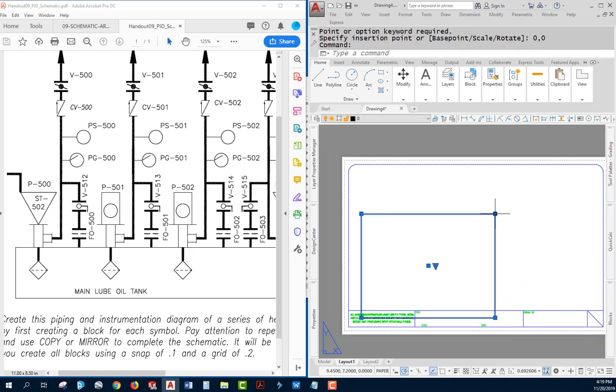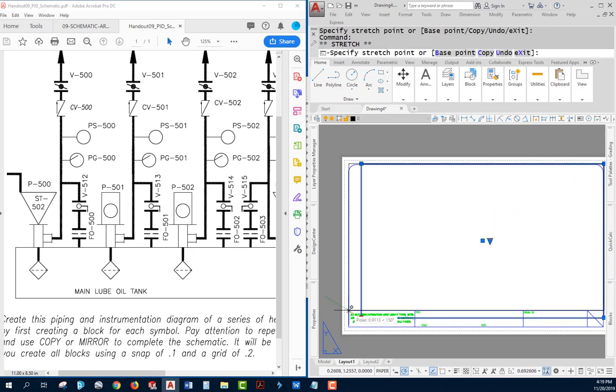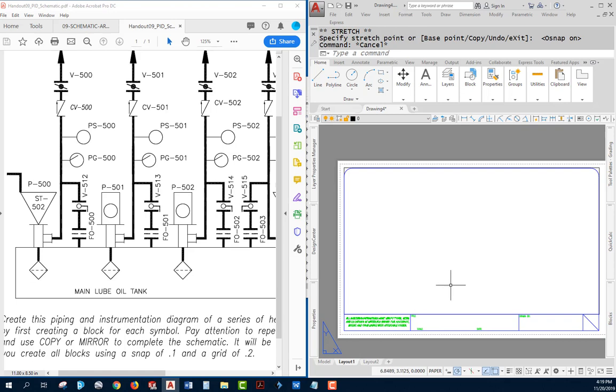I'm going to make my viewport a little bigger. Bring it out here. Bring it down here like that. Let me put my object snaps back on. Okay, I have object snap turned off because I was using a snap increment, but I'm going to leave them off actually. Now here's why I want the wipeout.